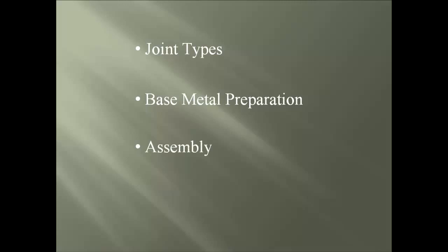Next, we review the assembly of the joint members, which includes the offset alignment that has tolerances ranging from 1/8 to 1/4 inch depending upon the bar size, plus the clearance between the bars, not only side by side but also end to end. Another quick tip: the welding of bars that cross each other is not allowed except when approved by the engineer of record.